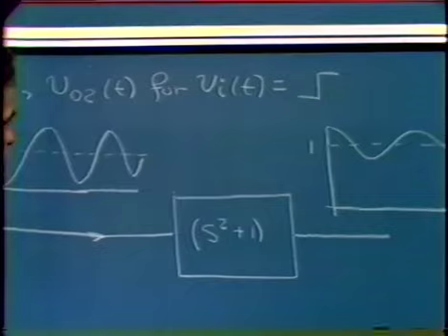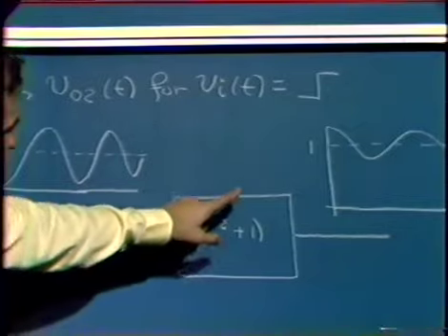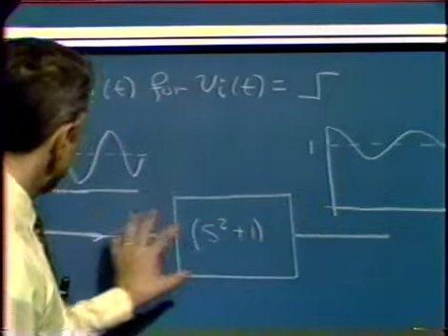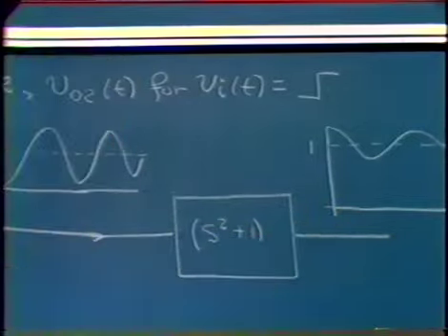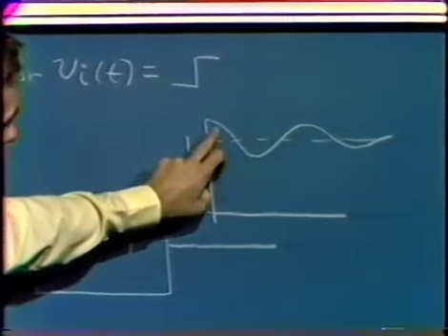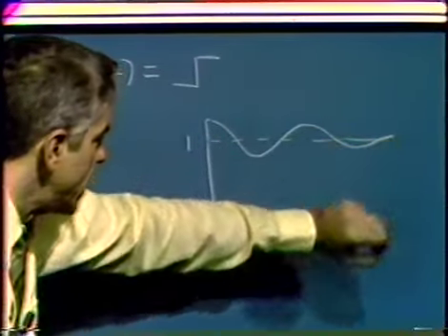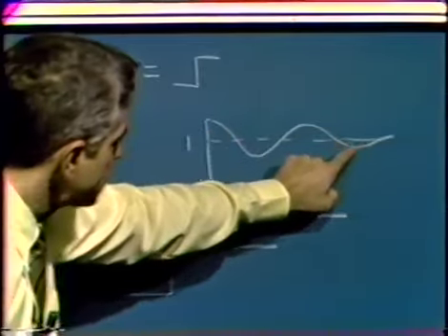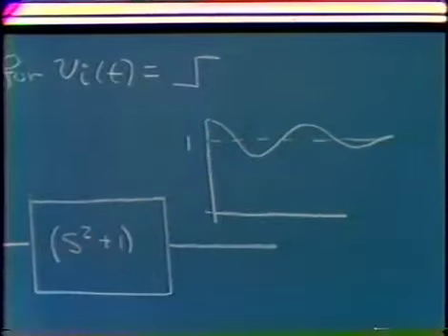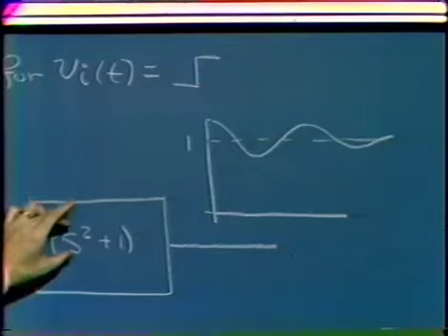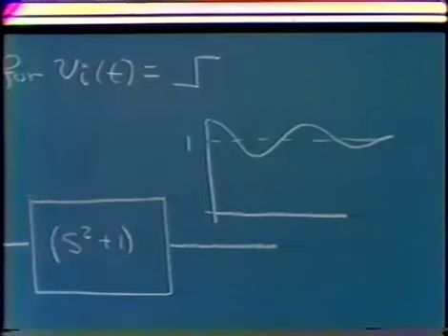Well, we can also argue that the initial value and the final value of the step has to be equal to 1 if we had a unit step. That's a fairly simple application of the initial value theorem and the final value theorem. And by putting those things together, we conclude that the step response of the overall system, the poles plus the zeros, is unity or very close to unity initially. It's unity at high frequencies, and what we get is just a little bit of residual of this sinusoid that's quite well filtered out by the complex conjugate pair of zeros.